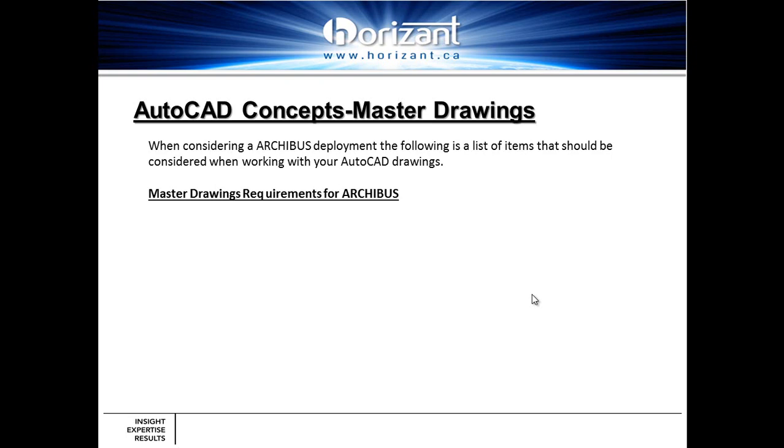There are several items you have to consider with this master drawing set. The first is a naming convention. As you have your master drawing set, you may have a series of drawings, whether it's 10 or 100, and you're going to want to come up with some sort of naming convention for those individual drawings. Those drawings are representative of different floors, so you may come up with a nomenclature that identifies the building and maybe a floor to identify that drawing name.